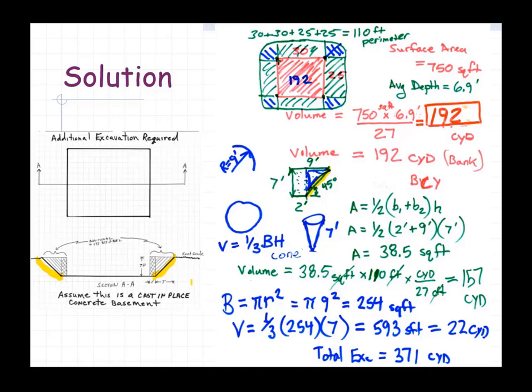I'm also looking to provide about 2 feet of working space for the construction of the foundation. So not just the wall directly, but 2 feet beyond the exterior of the wall in order to provide some working space to build that wall foundation.